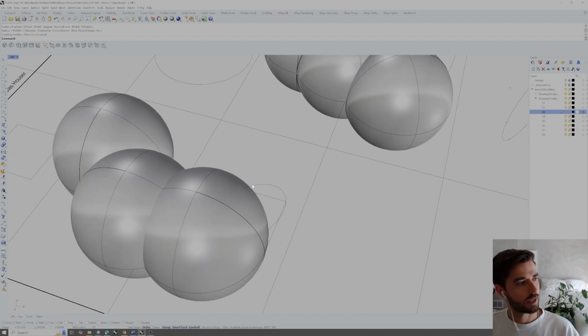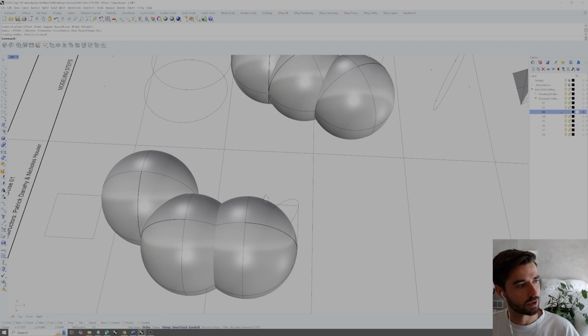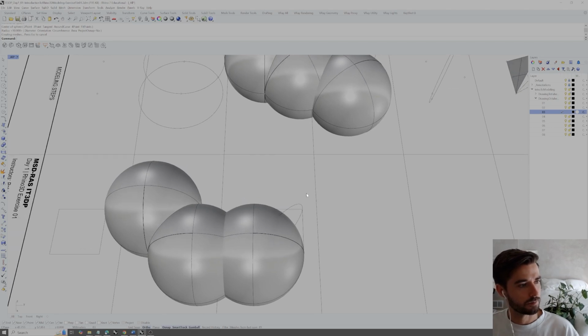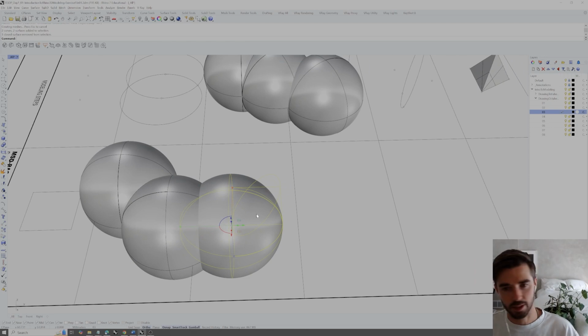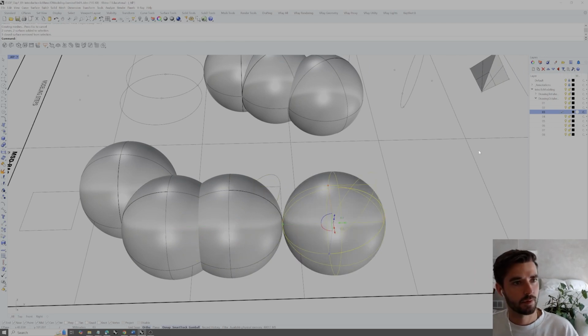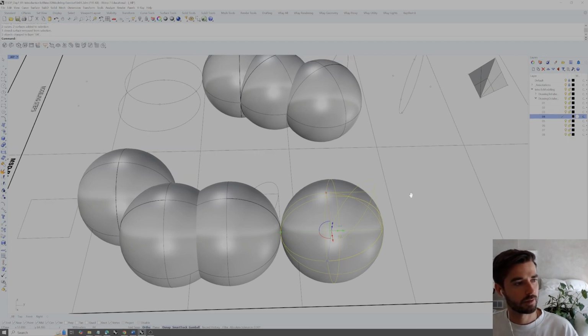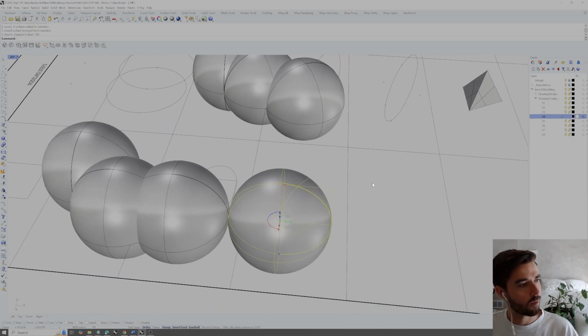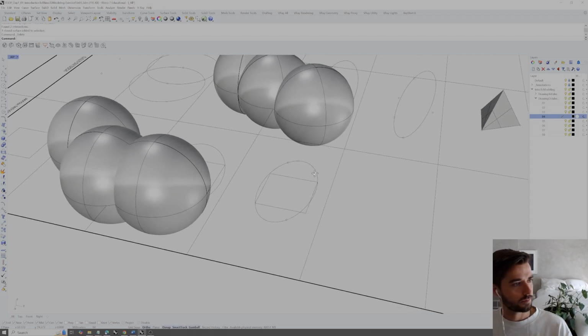And just like last time, we now have a point intersection, actually 2 points of intersection at the top and bottom. So similarly to previous ones, we're going to select all of our geometry, copy it up, change our layer, double click to be at layer 4, and now we can select the sphere and circle and type intersect, and then delete the sphere.